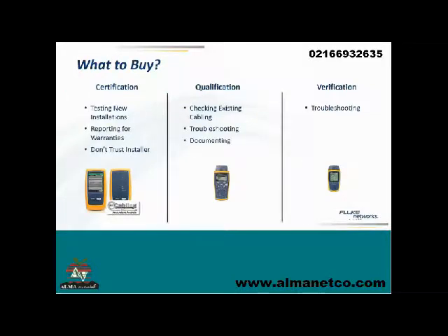A certification tool is really what you need if you're testing new installations. If you're building a new building and you're putting in new cabling, I'd recommend you buy a certification tool, or you hire somebody to do it, or you rent one of these tools. They're easy to rent, by the way. They're not hard at all. Also, the test results that you get from a certification tool can be given to a cabling manufacturer, and they will certify your cabling then for 10, 15, sometimes even 20 years of use, goodness. And the third one is if you don't trust your installer and you want to go around behind them and see what they're really doing, then you need a certification tool.